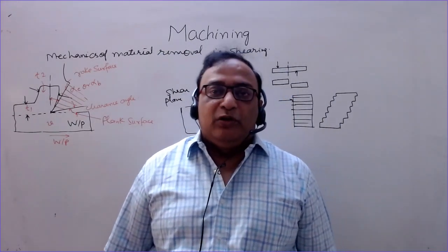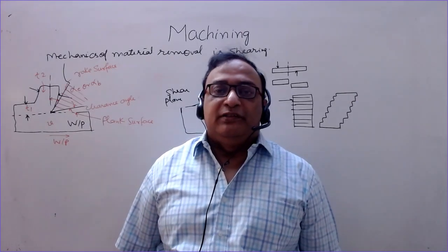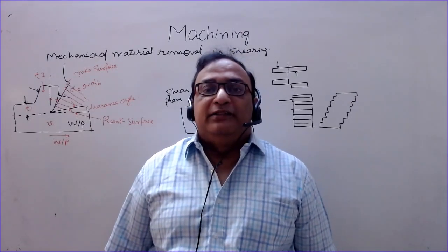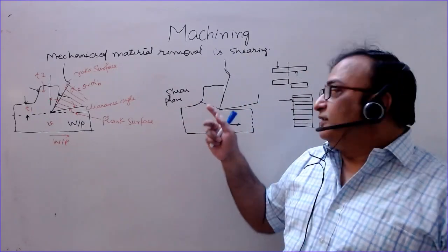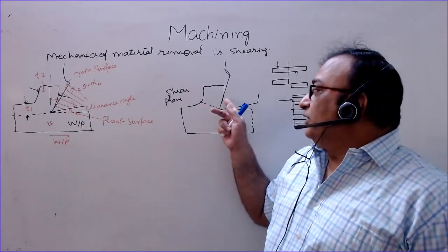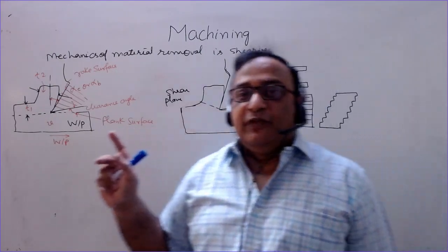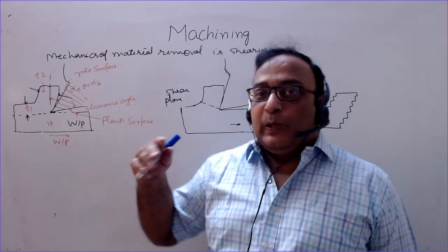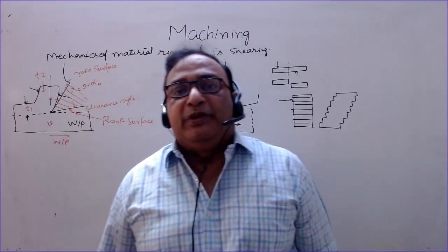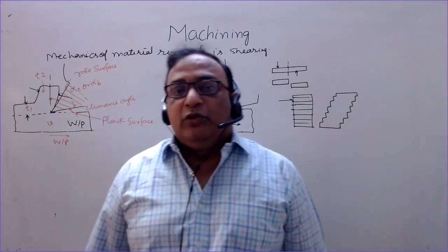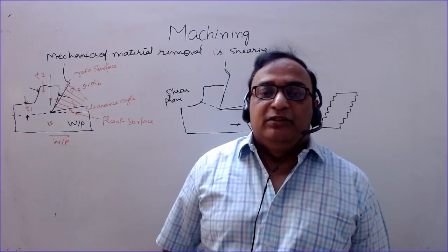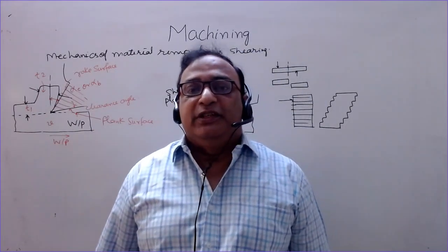Then some part of the face of the tool is broken and sticks to the moving lump of mass, that is chip, and it gets welded here locally. So as a result, when it is removed along with this chip, then the built up edges are formed. So it makes the tool weak, though it is advantageous to some extent, but only to some extent. So we will be discussing it later on.